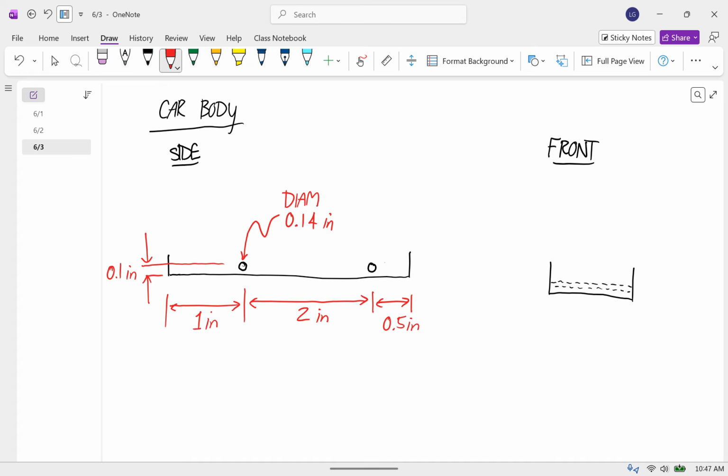And what matters is that this be somewhere around that 2 inches that we have between the 2 flanges. But we want to give it a little bit of clearance. Otherwise, those will press against the body and not spin. So again, I'm going to give this 1 millimeter of clearance. You could give it a millimeter on both sides, or probably a millimeter total is fine. So I'm going to go 2 inches minus 0.04, or 1.96 inches.